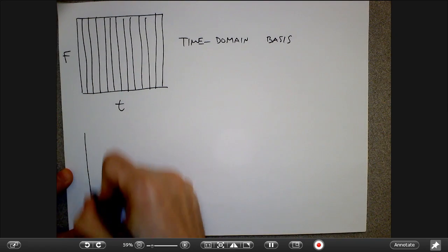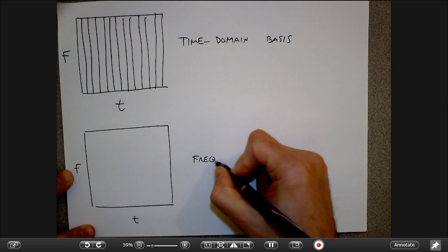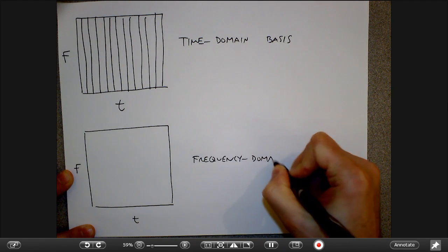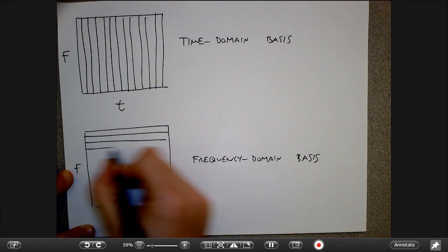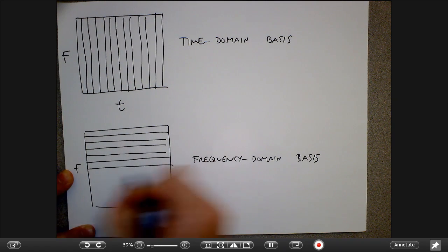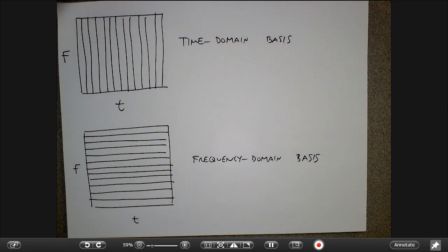So then we talked about the frequency basis, right? So a frequency domain basis is more like this, where now I can ask you to tell me the frequency content at a fine set of frequencies, but each of those coefficients, each corresponding to one of these rows, tells me about a sine wave that is spread out across the whole time domain spectrum. So there's no temporal resolution in a Fourier transform, right? I only get frequency that corresponds to the content across the whole signal, right?